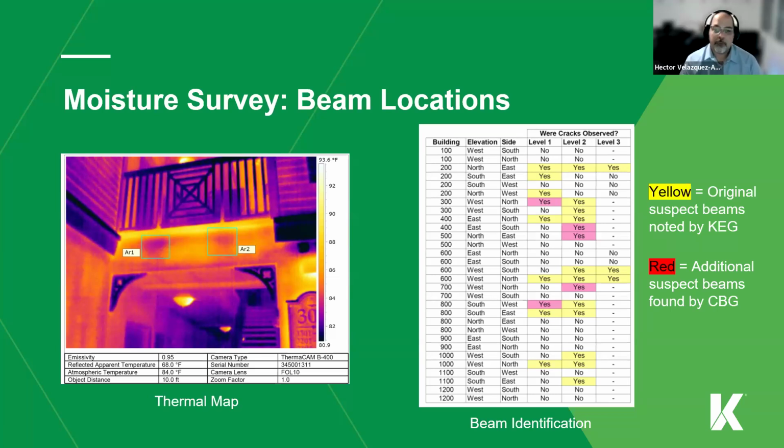Keep in mind, infrared is good to an extent. It doesn't necessarily show everything, and it is highly affected by weather conditions. If it's midday, it's not going to show the same thing as closer to dusk or early in the morning. It's going to show different values. So be careful when you are doing your evaluation with thermal imaging. And turn the lights off too while you're doing that. There are a few lights on in that picture, so that adds some heat.